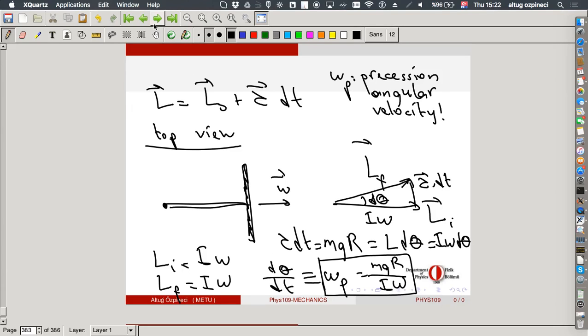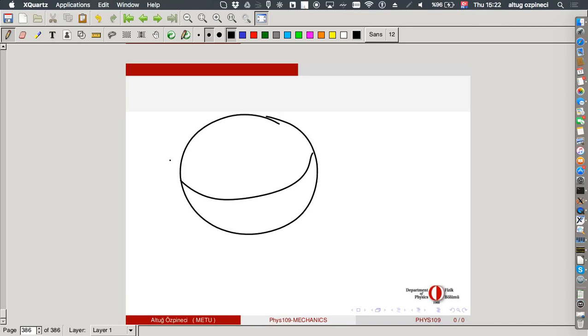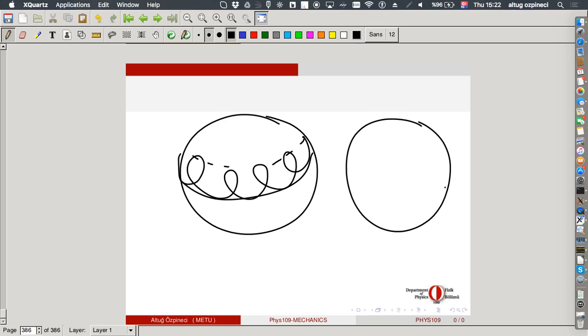Now, the actual motion of this gyroscope, you see, this is the gyroscope, will be moving on the surface. Just imagine this point, the distance of this point from the suspension point is fixed. So that point can be anywhere on this sphere. As this is precessing, it is not actually going over such a circle, but that point is mainly making such a motion. Depending on your angular velocity, the energy of the system, etc., it will be either making this motion or this motion.